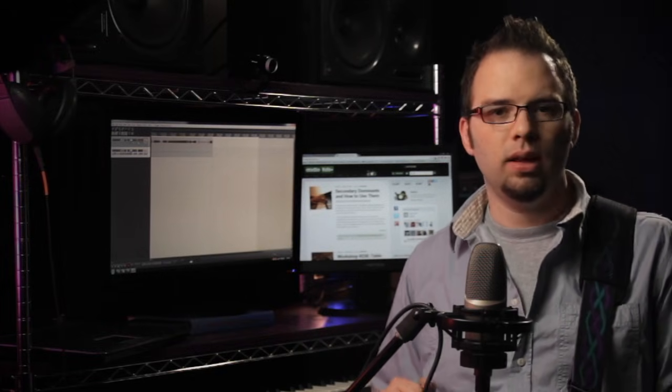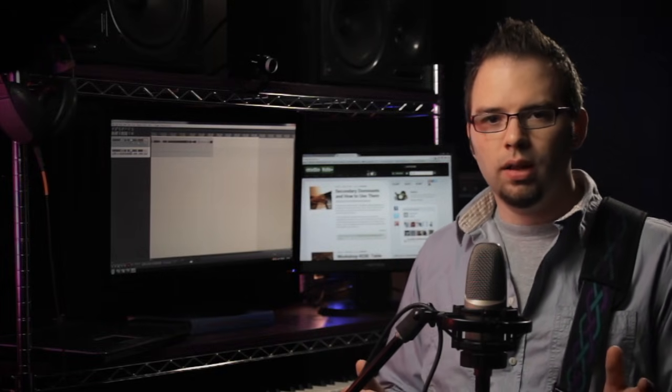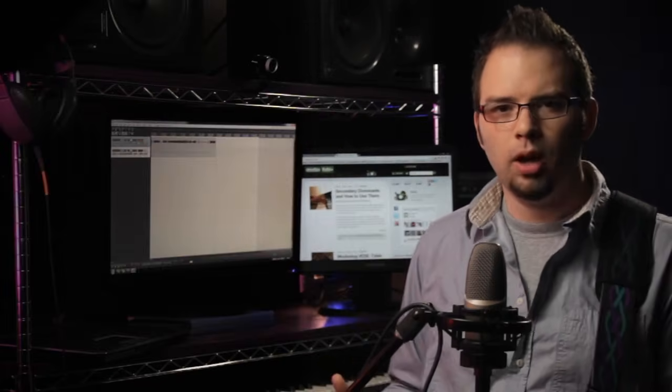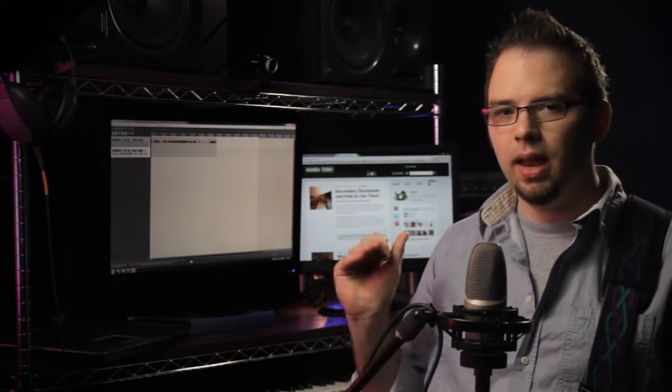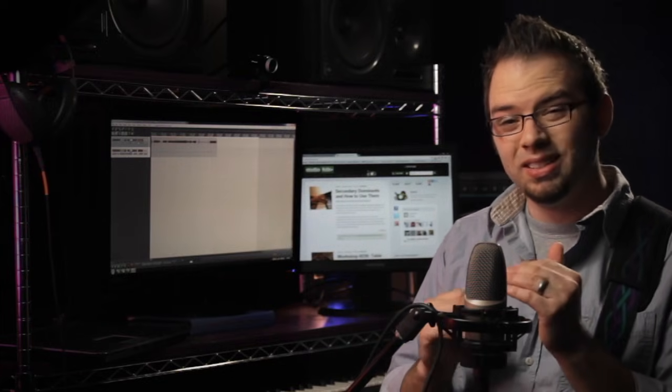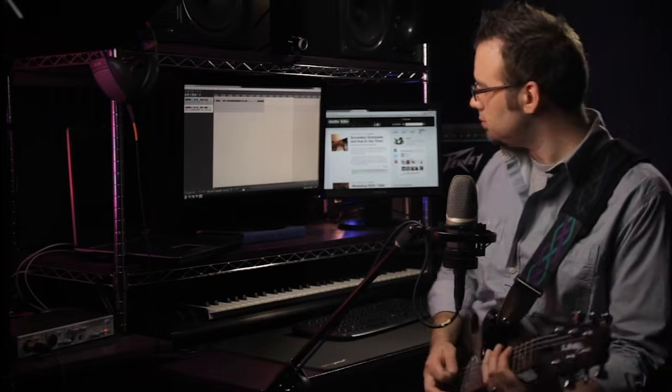Now, a lot of times in the recording world and the audio world, the volume spectrum is represented from -infinity to 0 decibels. 0 decibels would be the loudest thing. Anything above 0 decibels would be what's called clipping, and that's a type of distortion, and it's very, very bad. A pretty bulletproof technique is to take the loudest possible sound that you're going to get and make that -6 decibels. That gives you about 6 decibels of headroom, or kind of room above the loudest thing, and it gives you a margin of safety. So let's check out at this volume what we got going on here.